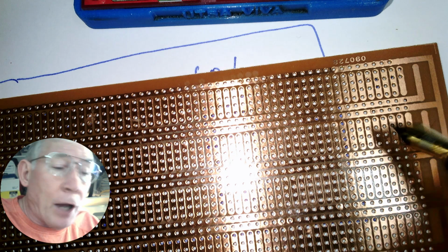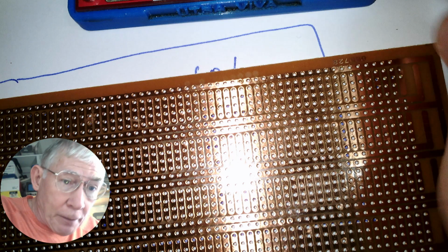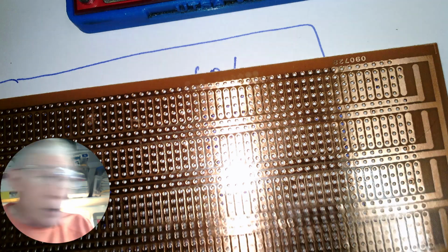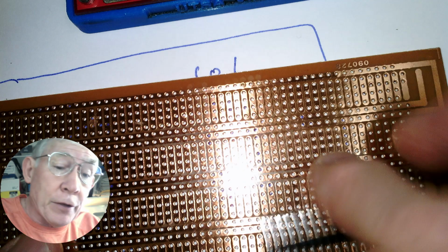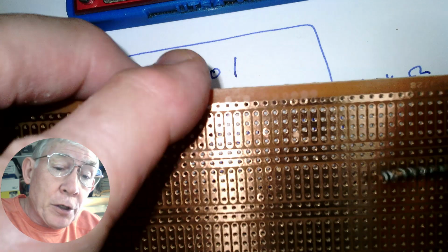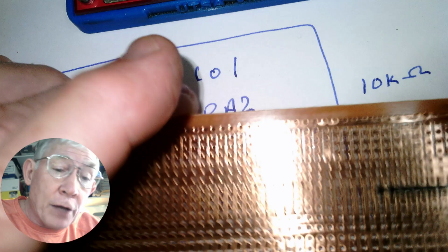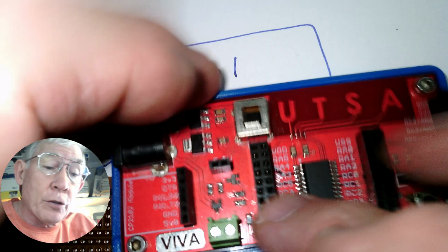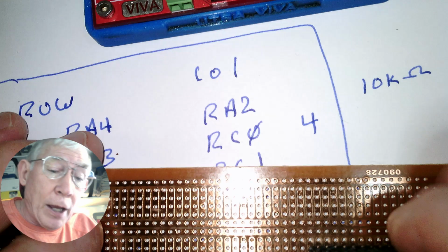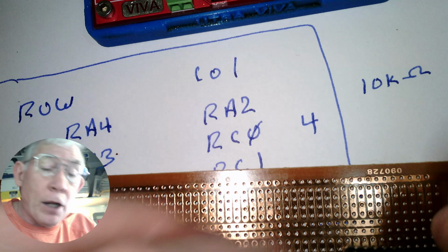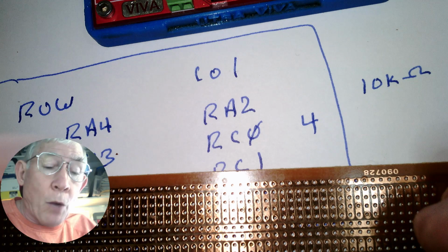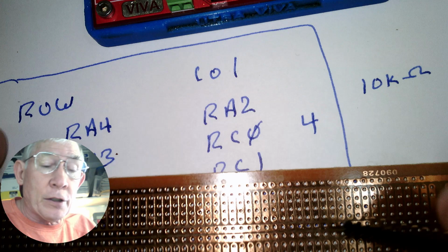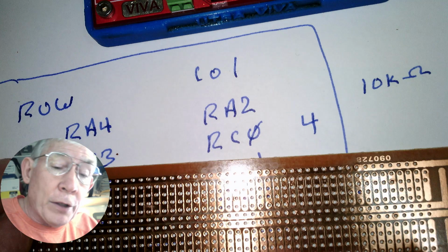So what I did, I just took a header in the form of this kind of a thing, and I just put it in here, and then I made sure I cut my piece out so I could have a 10-pin header and a 10-pin header here, spaced far enough that they would plug into my board. And then I put the 8-pin header in between them, and then I put the resistors and all the wires connecting everything together, and I soldered them on.